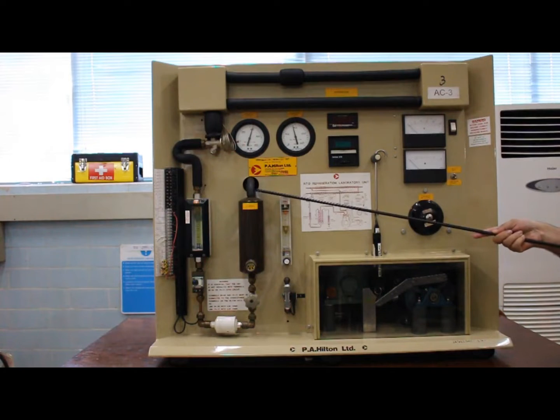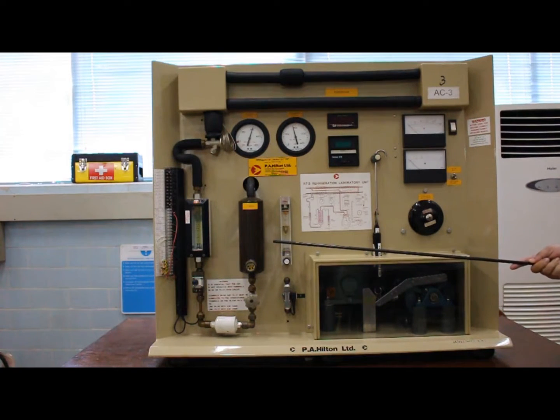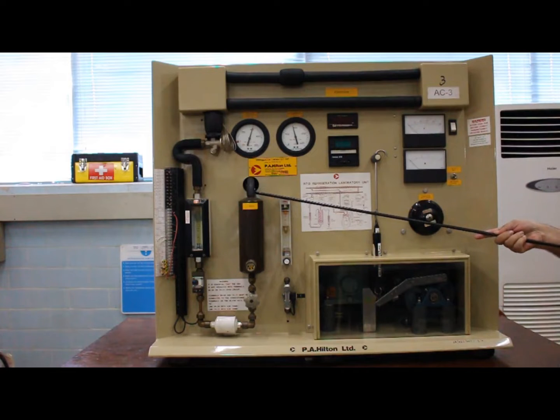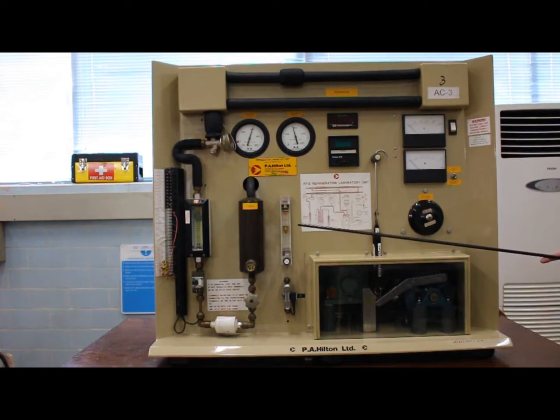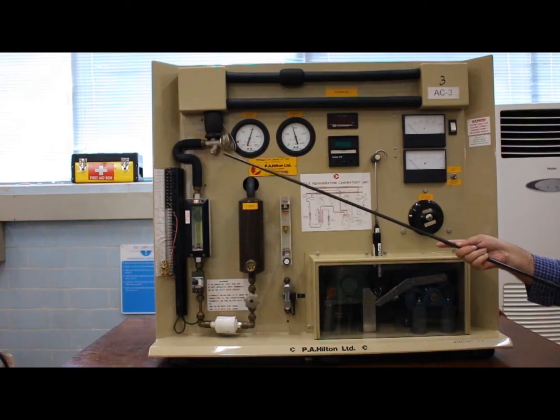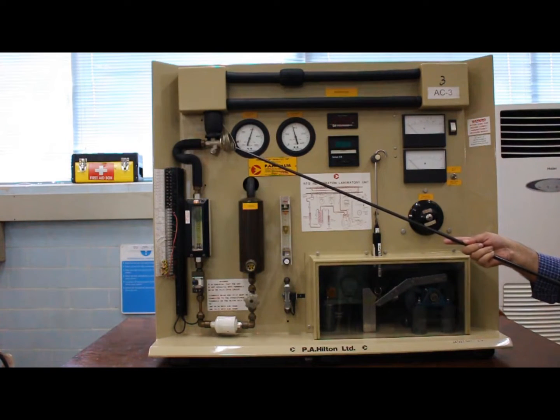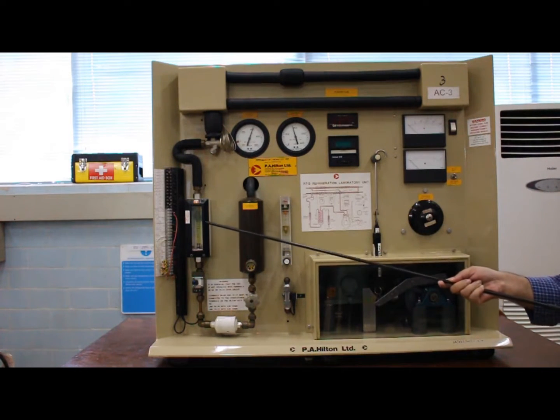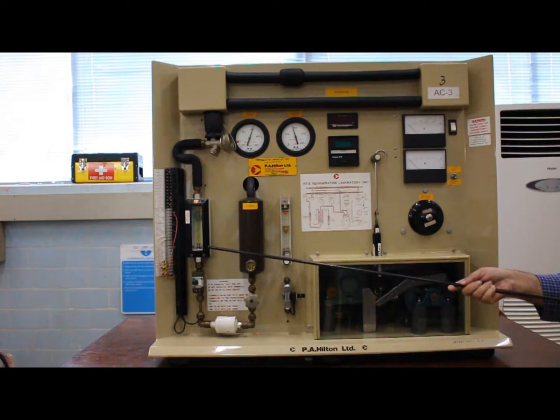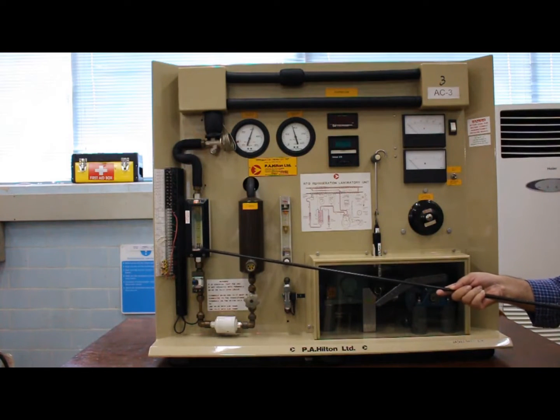As you can see, there are two tubes that are going to enter this condenser. One tube refers to the refrigerant that is coming into this condenser, and then it is followed by another tube which is circulating the water, which is taking all the heat from the refrigerant coming into the condenser. And then this condenser is connected to a coil that is a representation of an expansion valve or a throttling device. Over here you can see that there is a flow meter attached to it, so you can clearly control the flow rate of the refrigerant with the help of this flow meter.